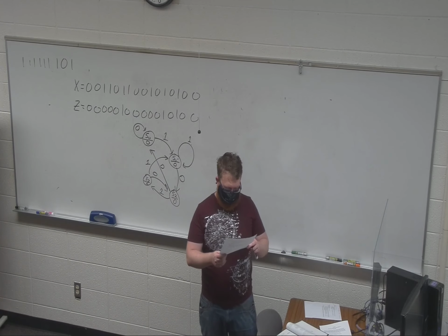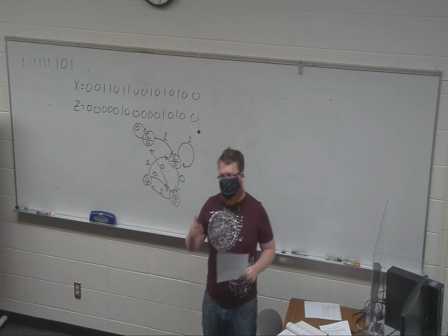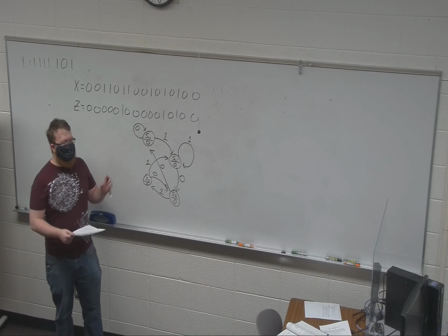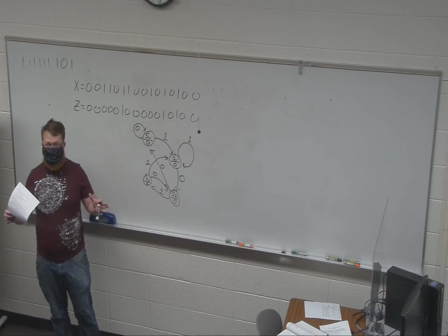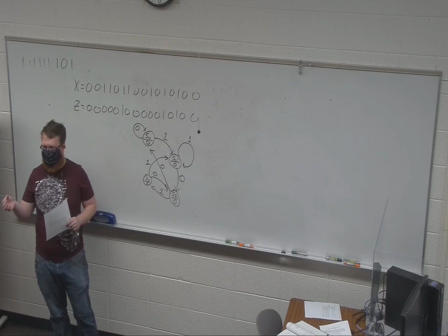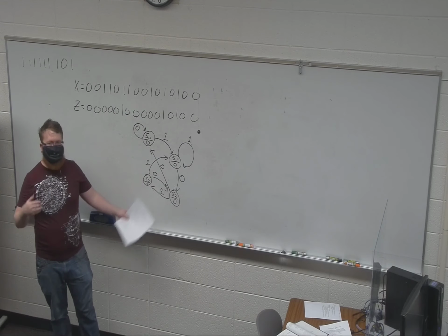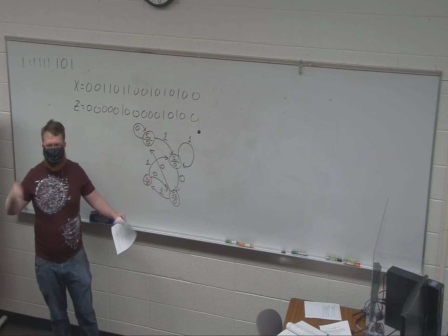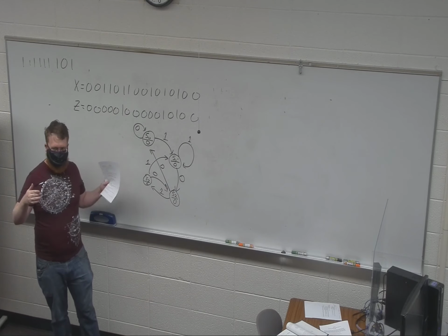Mealy, Moore. Oh, and that's the other difference that I forgot to point out. The Mealy can change as soon as the input changes. The output state can change as soon as that input changes because it cares about it. The Moore has to wait until that next clock edge to update because it has to wait for a clock edge in order to change states.